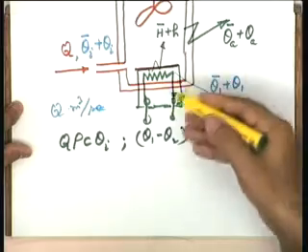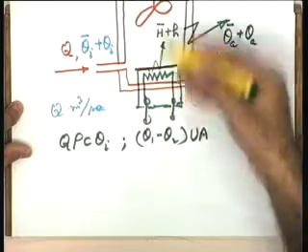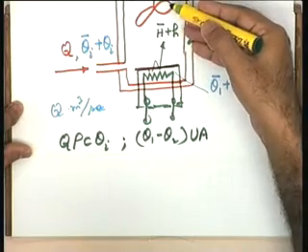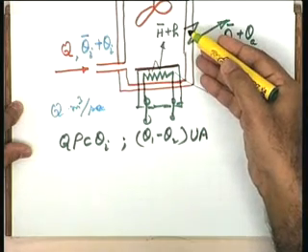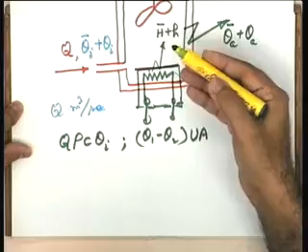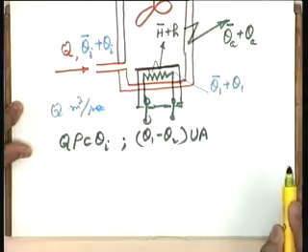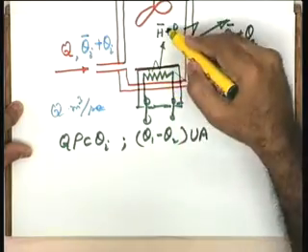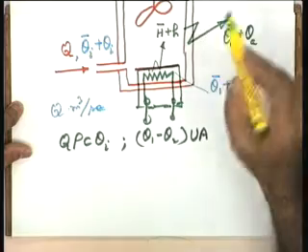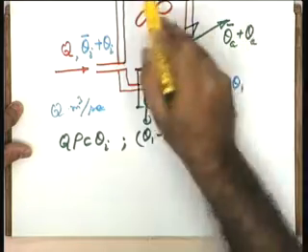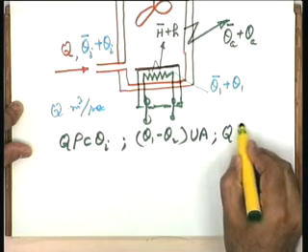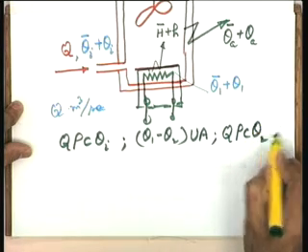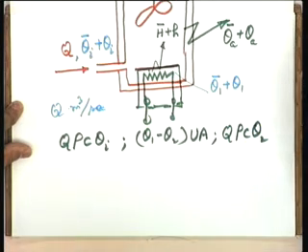This is the source, this we have already seen. This is the heat given to the liquid, it is the input for the liquid, it was output for the heater mass, becomes input for the liquid naturally. Okay? This is as far as the heat flow rate from the heater to the liquid is concerned. Coming to this now, what is the heat carried away by the outflowing liquid? Is it not identical? Q rho C theta 2 joules per second. It is the heat carried away by the outflowing liquid.